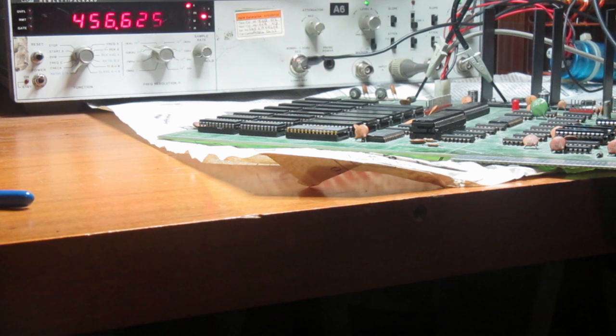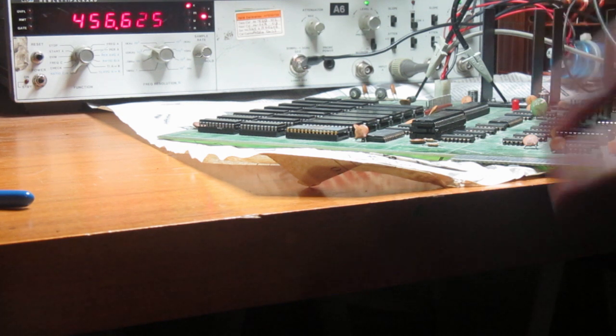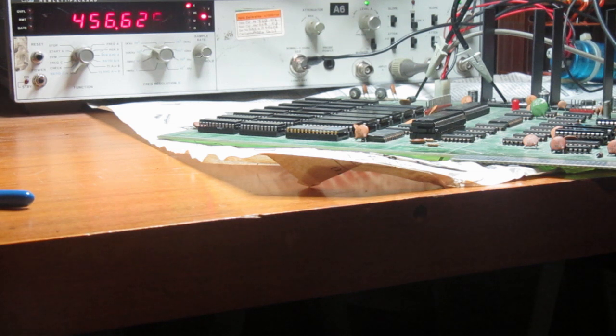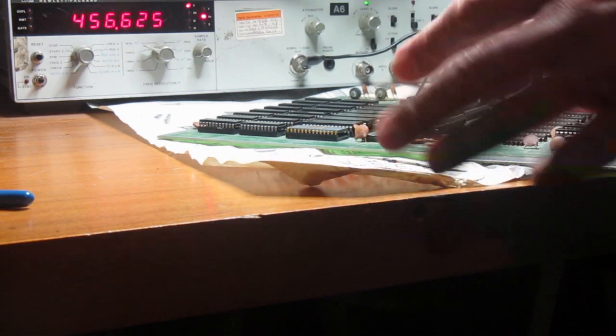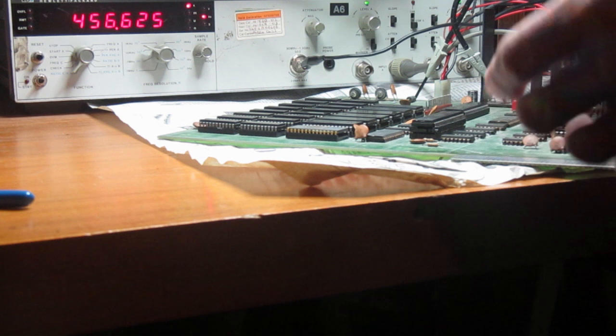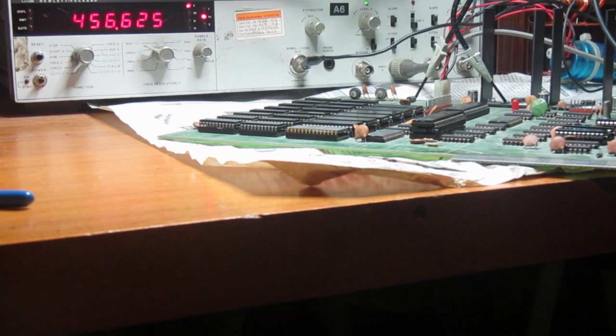If you have an oscilloscope, you should check that there is no evident address bus or data bus conflict, so signals look normal, and we just want to try debugging the address distribution and the address decoding logic.